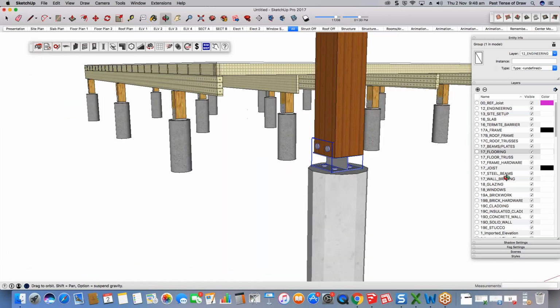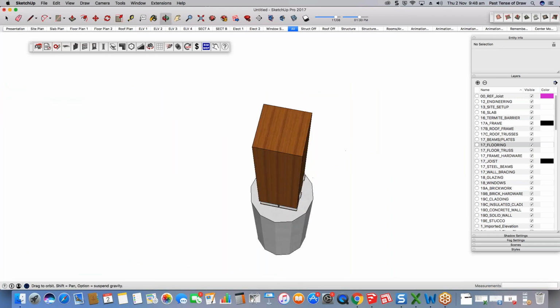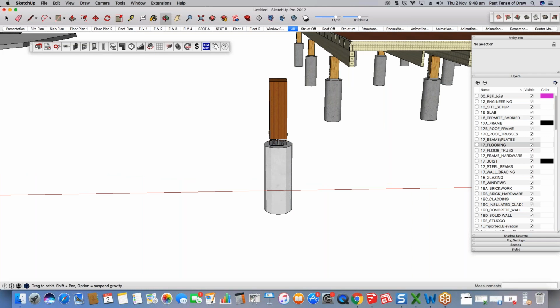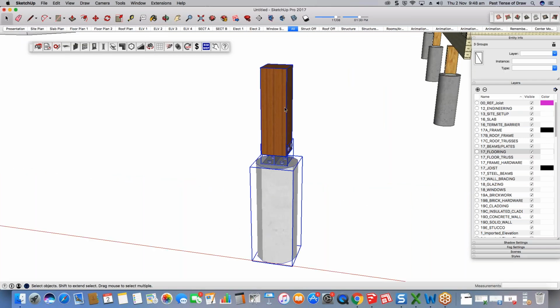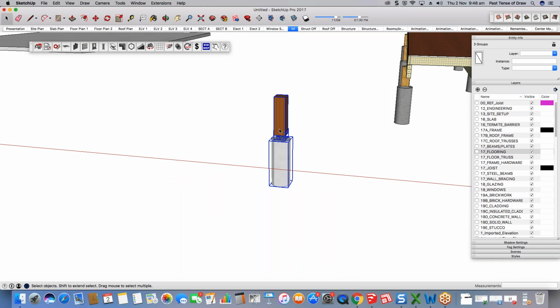Now that you've done that, as long as you're happy with where it's sitting and it's aligned appropriately, you can then select everything by left-clicking, dragging, highlighting all of the items, and you can even turn it into a component or a group. Now, the difference between a component and a group is just a standalone item. If you do turn it into a component, it means that if you do make a change, every single one will adapt to that change. They're basically a clone.